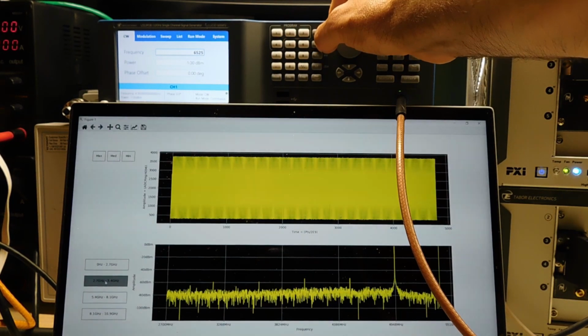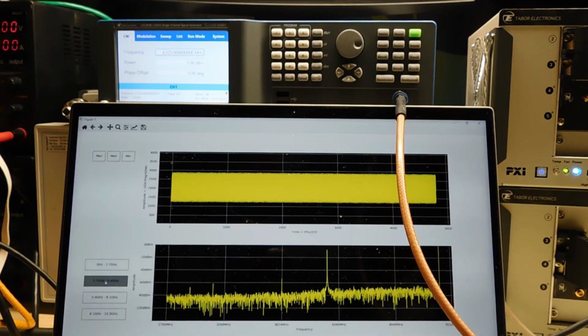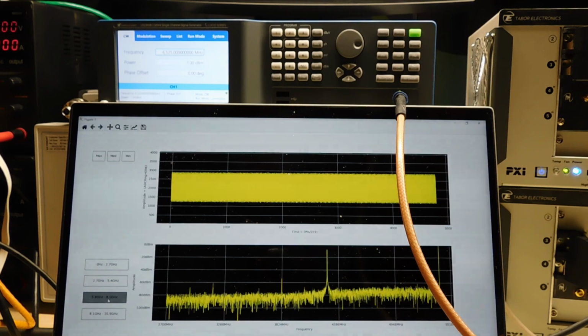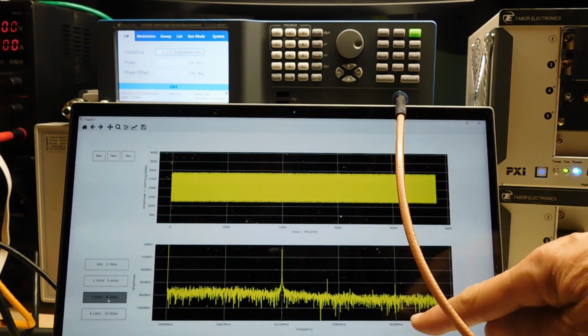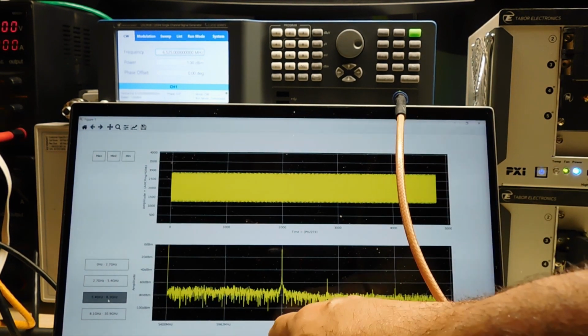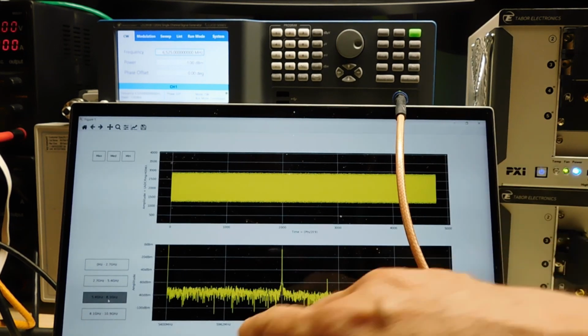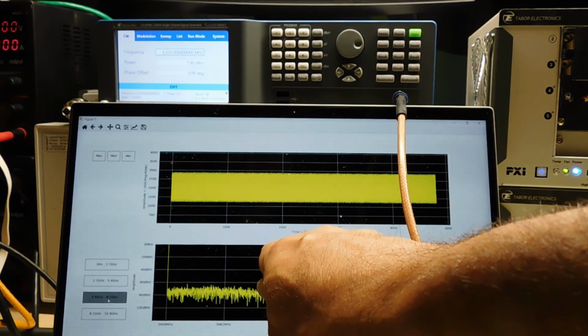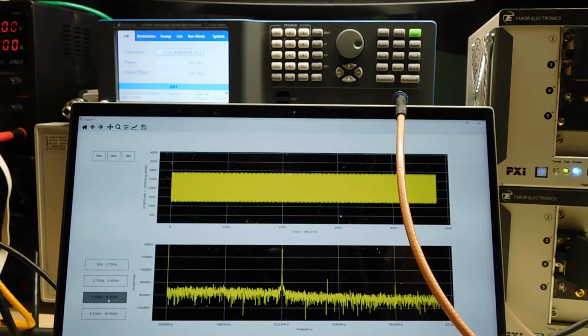6525 megahertz. Okay, now you can see the signal shifted again down, and what we need to do now is uninvert the spectrum and just adjust the markings along the bottom, and you can see now 6525 megahertz is just there. And now you see in this third Nyquist zone that the amplitude of the signal has slightly gone down. Frequency roll-off in each Nyquist zone is related to a sine x over x function.